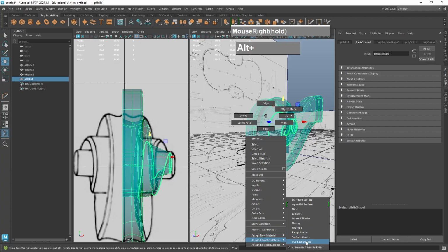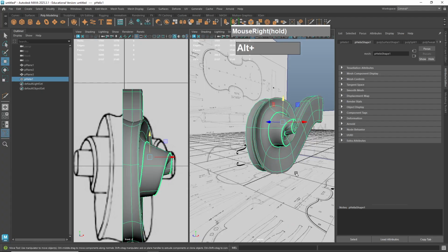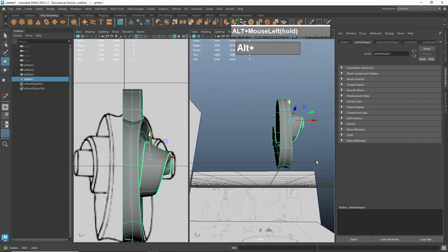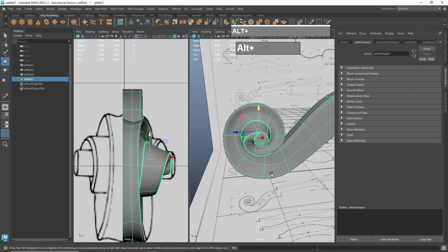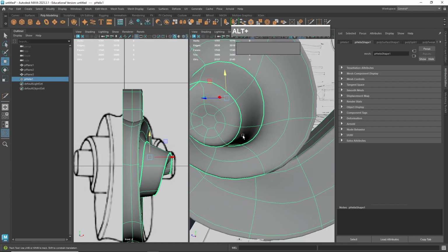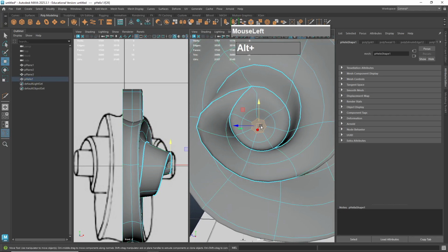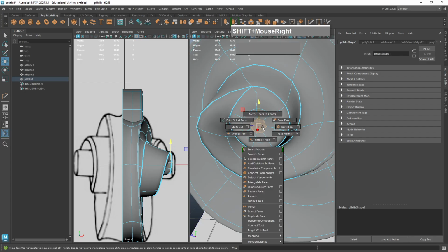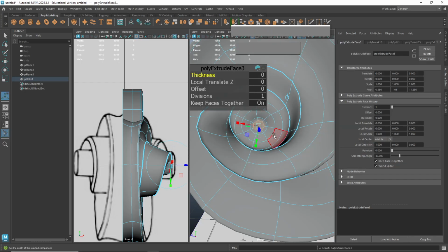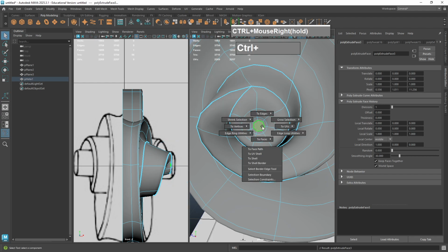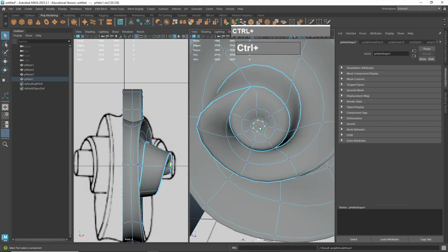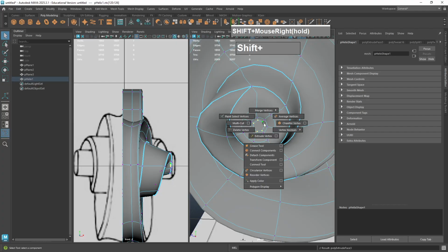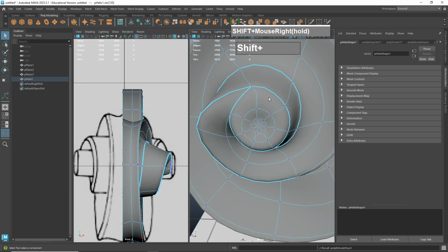Okay, I'm going to switch this back to the existing material, the Lambert 1 material again, and then let's take a look. Alright, doesn't look too bad. Okay, of course there's still some refinement that we need to do. Maybe I want to collapse these vertices into itself. So maybe I'll extrude again. And then I will hold down Control, right mouse click, to vertices. Then I'll hold on to Shift, right mouse click, and then say merge everything together. Yeah, like that.